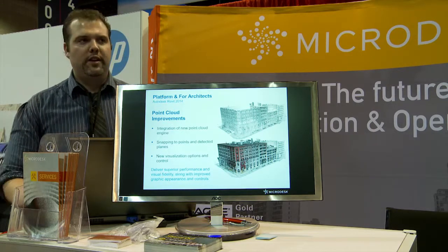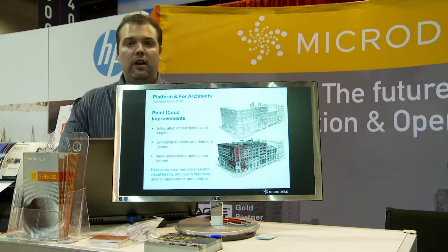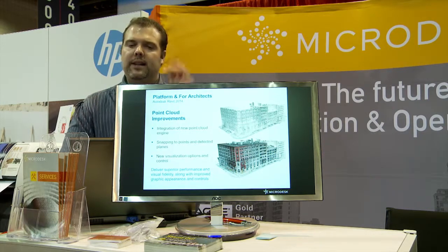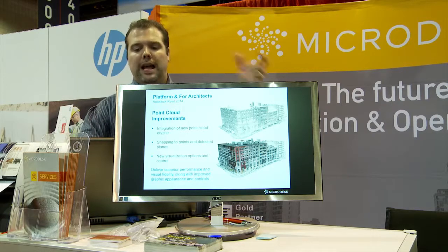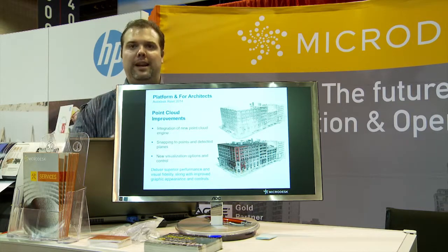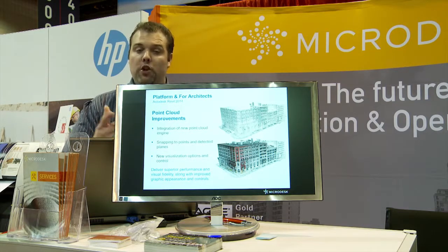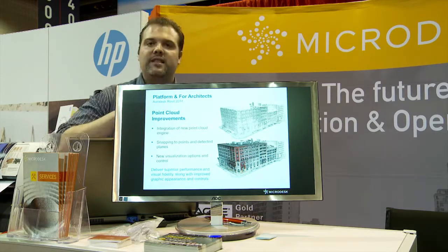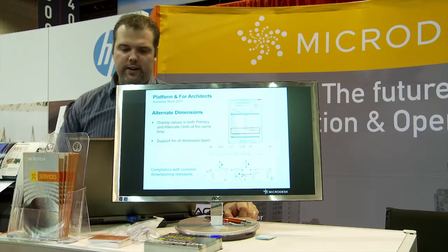Recap is that new feature that comes in the Building Design Suite, but you can also download it for free without having any of the Autodesk applications. Recap is a middle platform where you can drag in that point cloud from whatever source, and it allows you to bring it into Revit already manipulated. You can crop it, chop it, and easily bring down the file size and the area that you need. Not only that, but you can use the point cloud file, snap to it and actually draw things on it. So again, that was a very, very good enhancement.